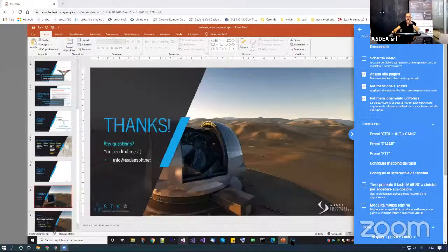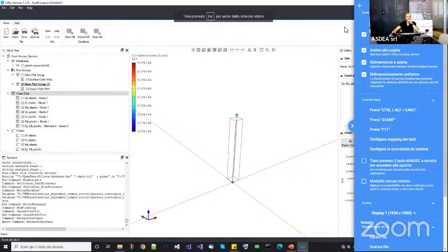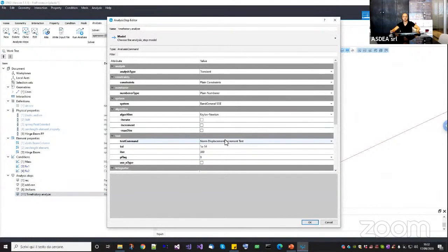So let me share my screen. When you choose the values for the norm unbalance, you have to take into account a couple of things. As in this case, I was doing it for the norm displacement. Well, first of all, you have to keep in mind what are the units that you're using. So for example, in this case, I was using Newton and meters. So that's why I said for me, a check on the displacement equal to 1 to the minus 6 is fine because it's 1 to the minus 6 meters.